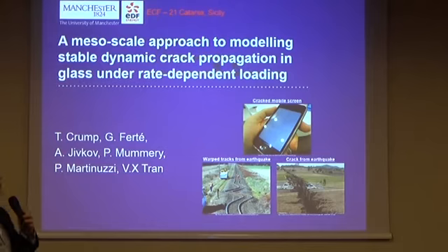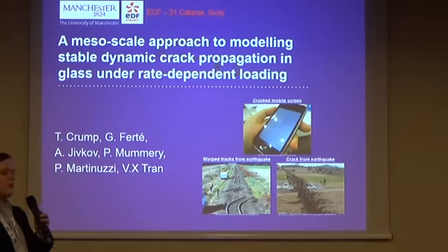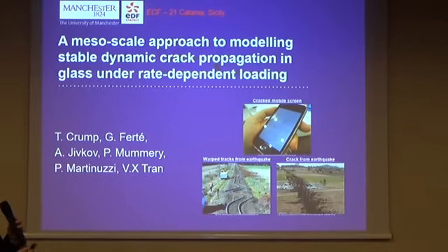In particular, lifetime extension of the UK's nuclear reactors, and we're looking at dynamic effects of initial cracks within the moderator bricks, which provide the structural integrity to the AGR cores, and so therefore we're looking at energetically conservative manners of looking at crack propagation in dynamics.